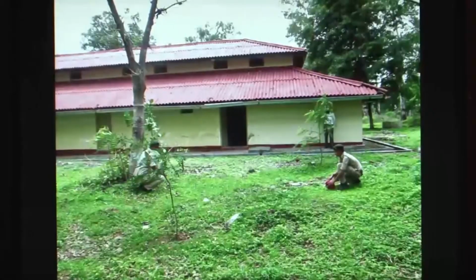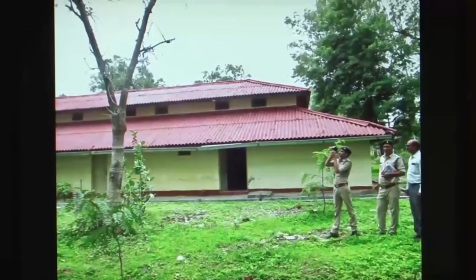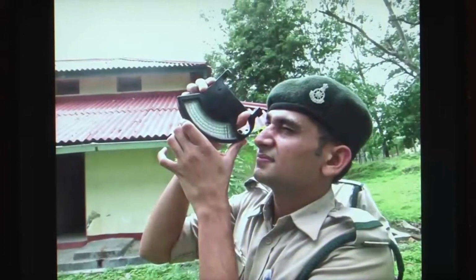To measure the height, you would first measure the distance from the base of the tree, which you can do with a tape or with a range finder or maybe with your steps. Then you would stand to one side and arrange your instrument such that your eye, the circular hole that is your optical hole, the crosshairs in the front and the top of the tree come in the same line. Then you would press this button. When you press this button, the pointer has become fixed and then you can take the readings from the scale. But this instrument also does something very smart.